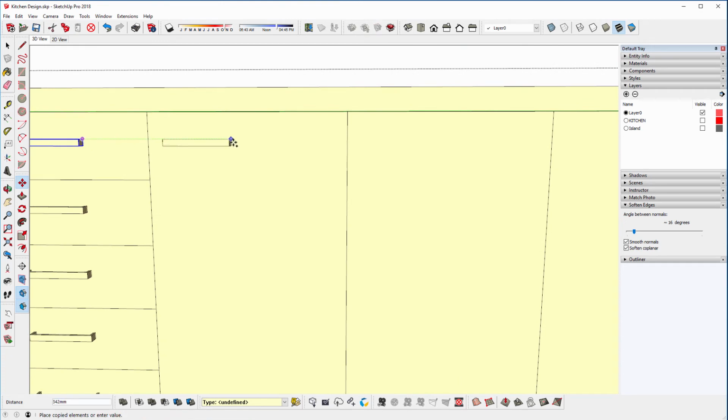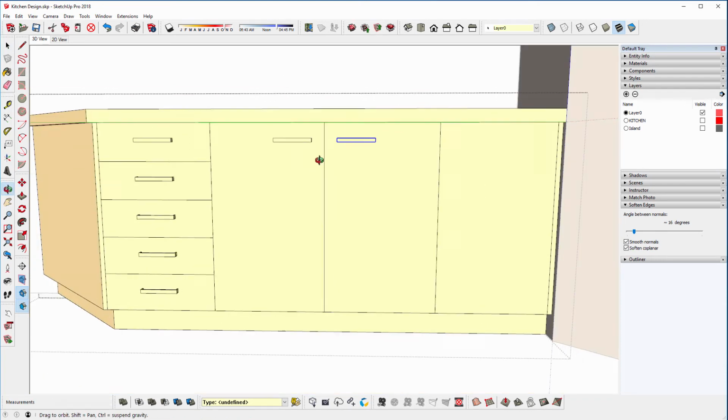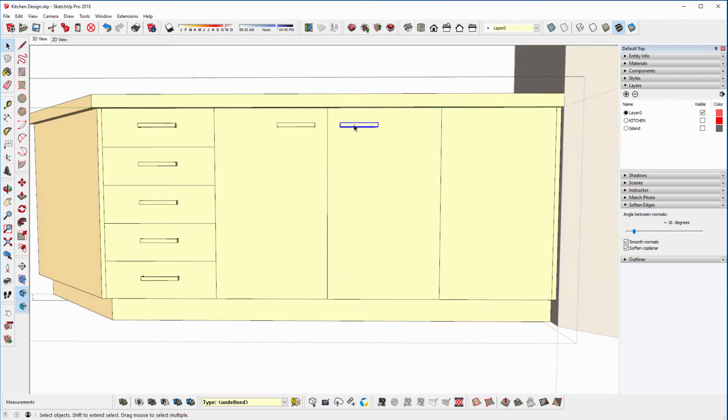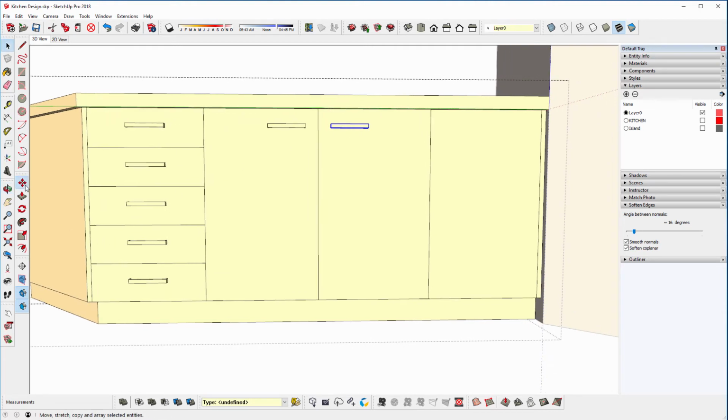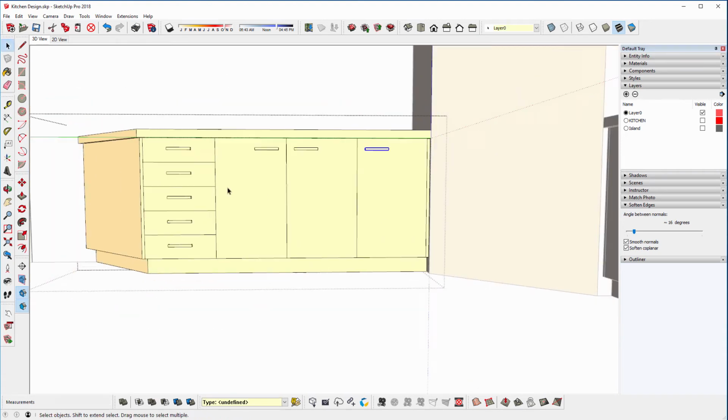So move tool again, plus Control to the edge, and then maybe I come in that way 25 or 50. And I could copy that on the green axis, so left arrow until it hits the edge, and then come in 50. Once you've got those two, you could use this one that's still selected, get the move tool, and use that endpoint there to copy to there. And see it now remembered the 50mm spacing at the top.